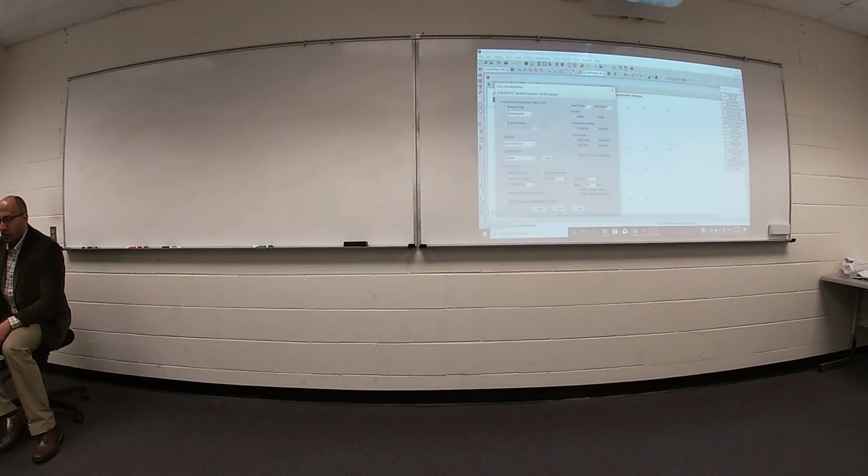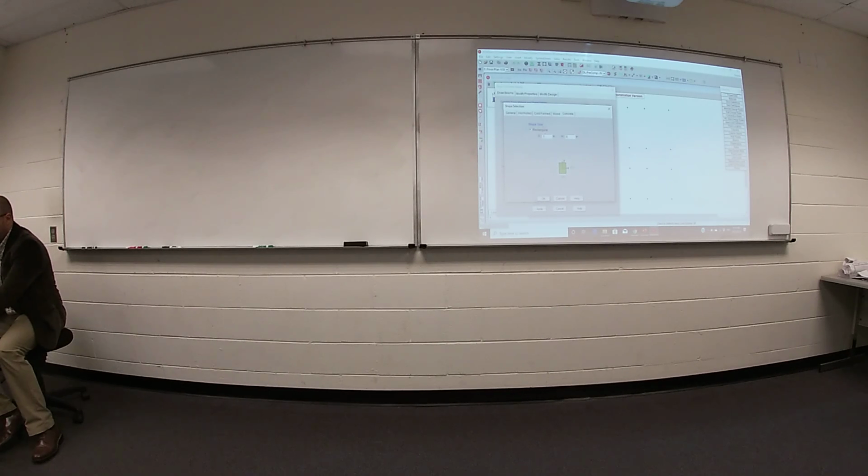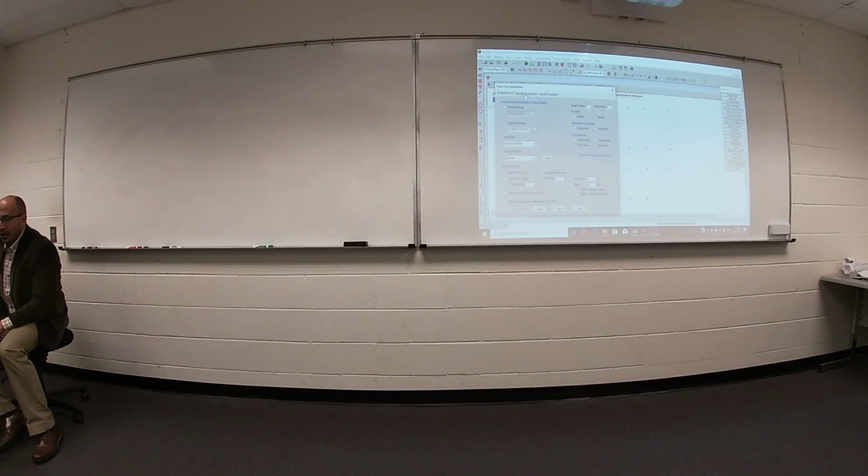If you remember, we will define explicit shape, your design or your cross section from this icon, your depth 30 feet, your width 16 feet. Okay, one more thing, modified design. This cross section will take it.